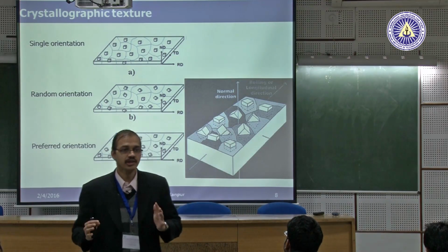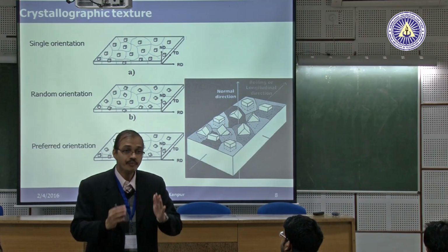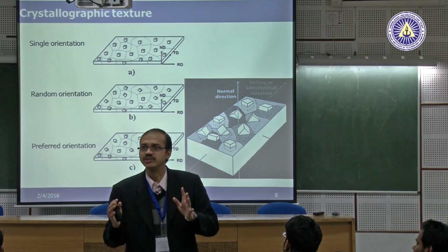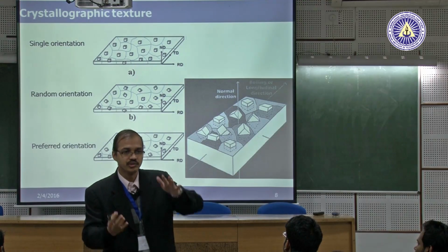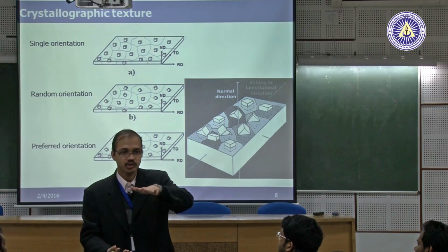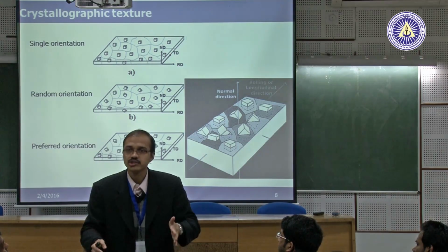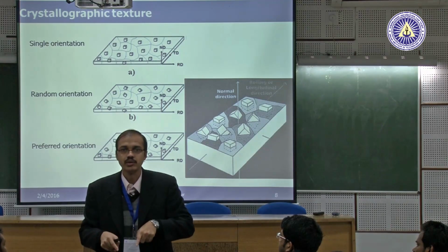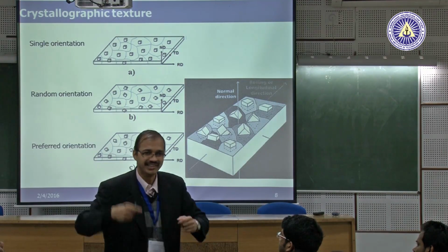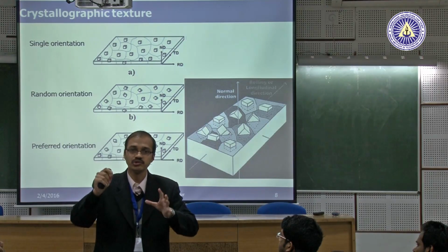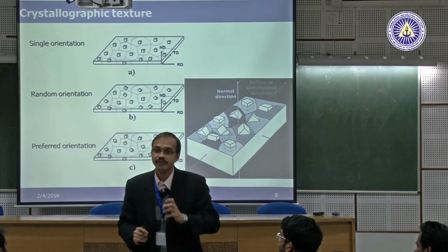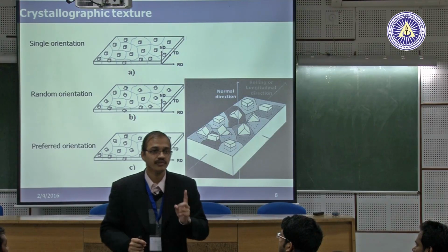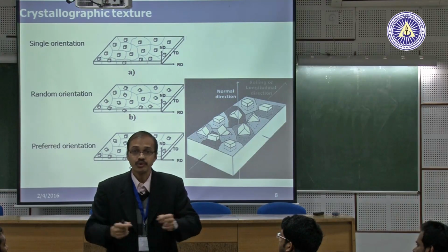You have seen a car body, right? See, I worked in Tata Motors for 10 days. Okay, so I tell you, if you go to Tata Motors, they have these big blanking presses. What they do is they have this rolled strip of steel, and you just punch it. You punch it, and then what comes out is your car door, and then they put in a lot of plastic and all goes in. But this is how you make the car body. Now, when you are making this car body, you want your material to deform very easily. Yes or no? Because you want to give the shape.